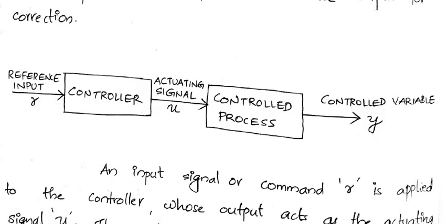With the help of a controller, we were actually generating an error signal based on the actual temperature inside the furnace and the desired temperature, and that error signal was actually fed back to the input side to control the relay circuit.